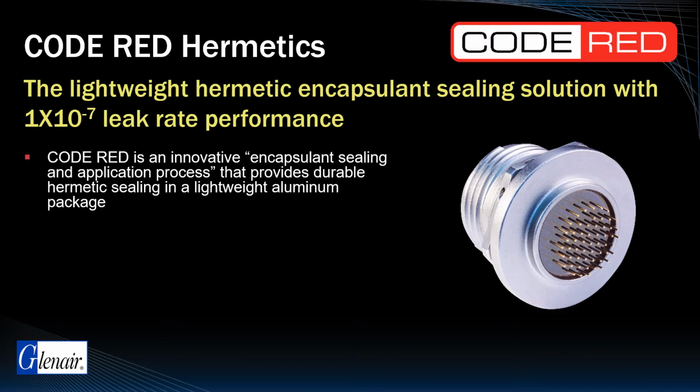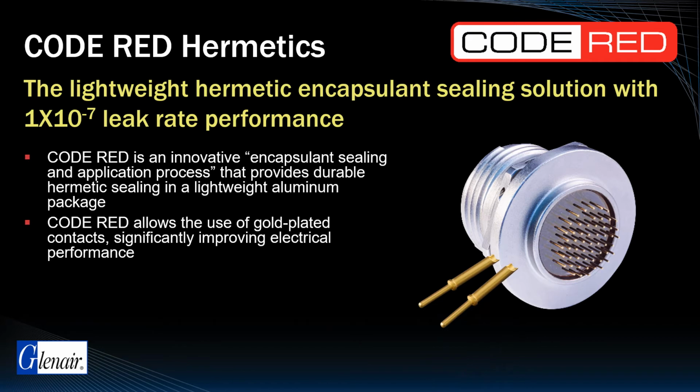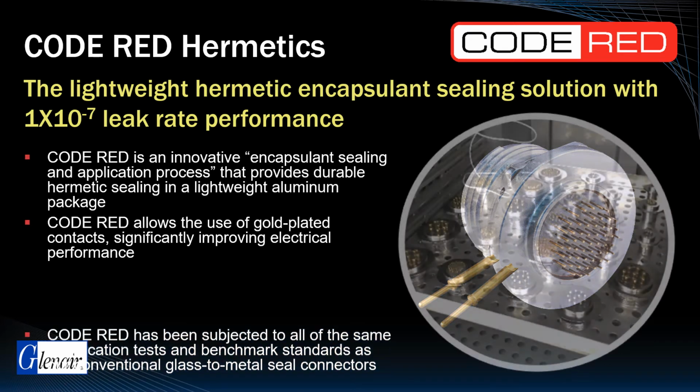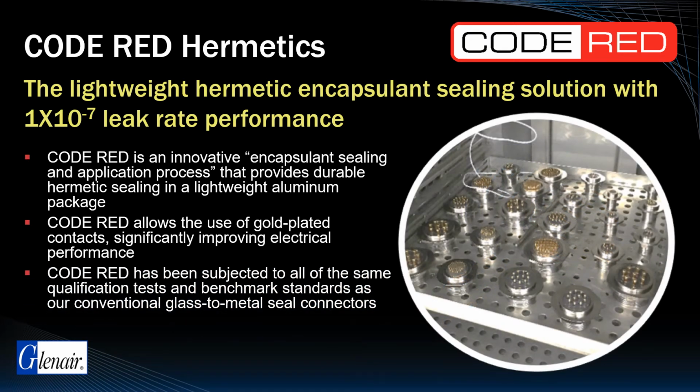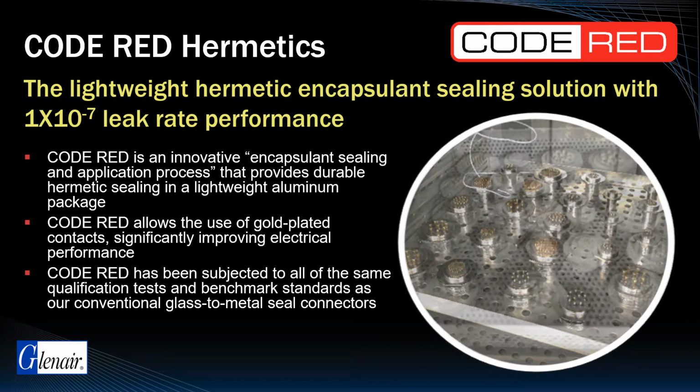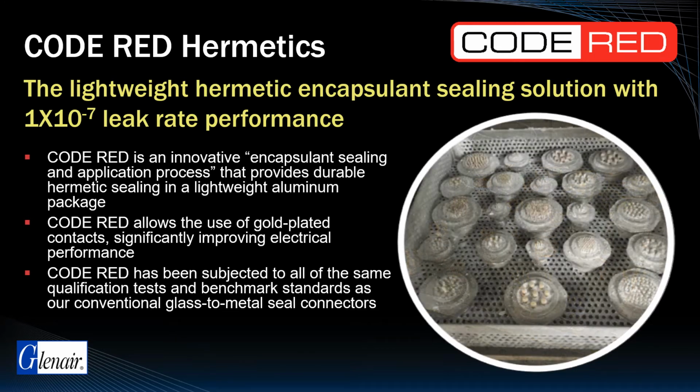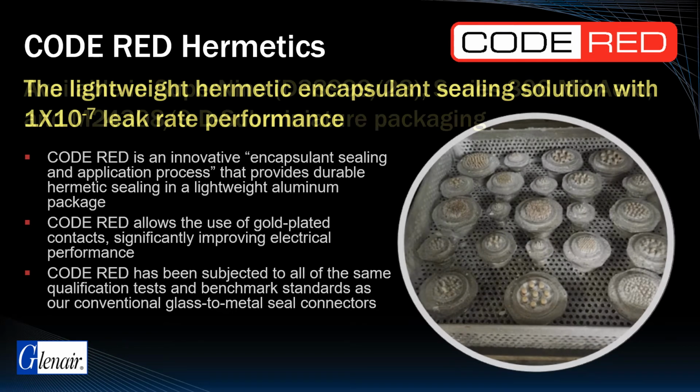Further, CodeRed hermetic connector configurations incorporate gold-plated beryllium copper contacts as opposed to the iron alloy contacts used in glass-to-metal seal designs, significantly improving electrical performance. The material and processing have been subjected to the same qualification tests and benchmark standards as our conventional glass-to-metal seal connectors, including 100 cycles of thermal shock, as well as highly accelerated life testing, or HALT.